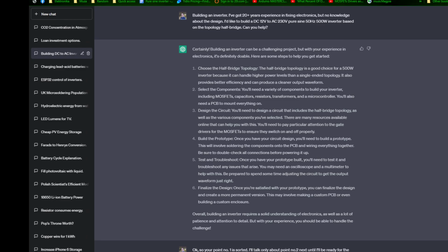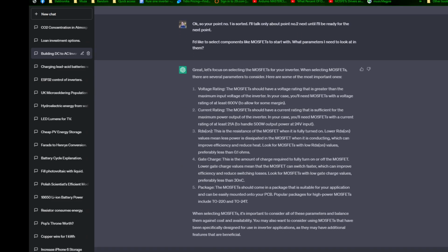So I said, okay, so your point number one is sorted. I'd like to talk about point number two next, until I'm ready for the next point. I know you shouldn't add it, but it's okay. I'd like to select components like MOSFETs to start with. What parameters do I need to look at in them? Yes, great. Let's focus on selecting the MOSFETs: voltage rating, current rating, RDS on, gate charge, package, and then when selecting MOSFETs, blah blah blah.